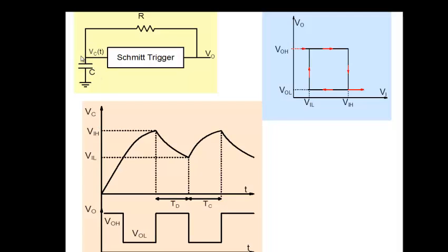And this is at the input here. At the output, Schmitt trigger has only two states: high state and low state here. So at the output, you will see a V0H, V0L, V0H, V0L. And therefore, you have an oscillator. You have an oscillator where all that we have done is we've taken a Schmitt trigger and connected an R and a C, and you get this oscillation. So very simple oscillator, and one can analyze this and show how to choose the value of the charging time.